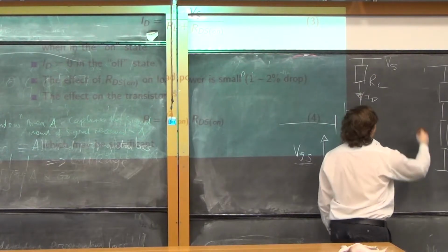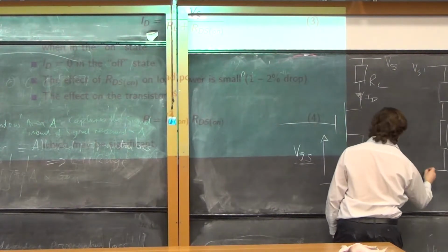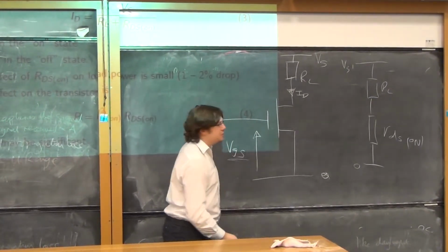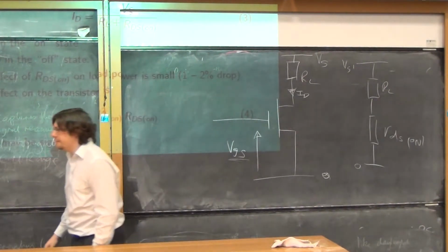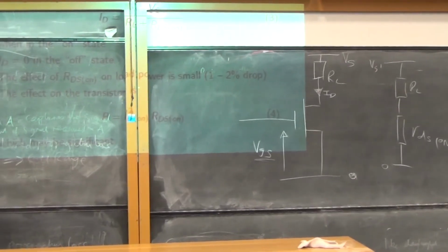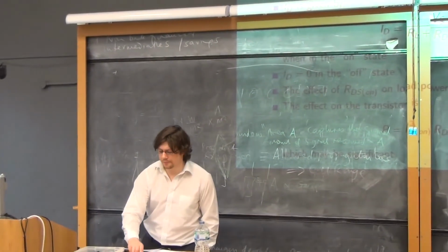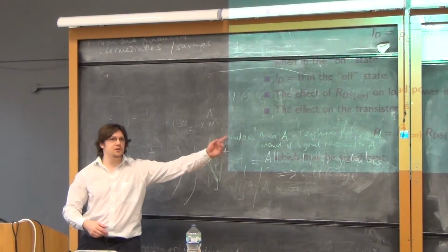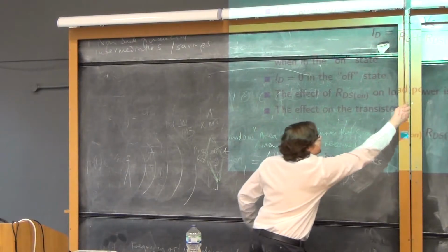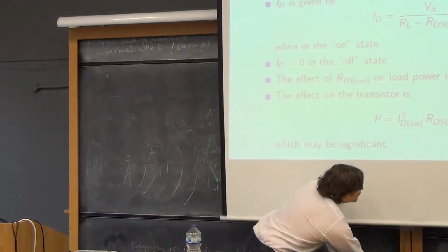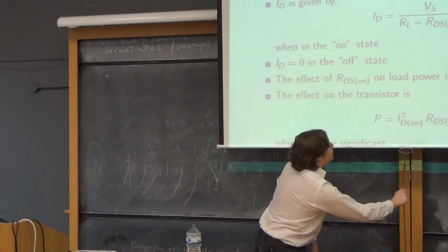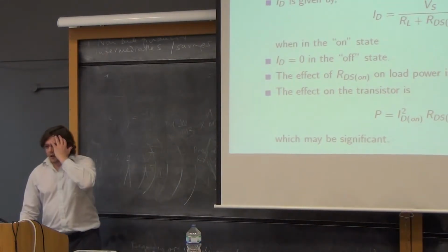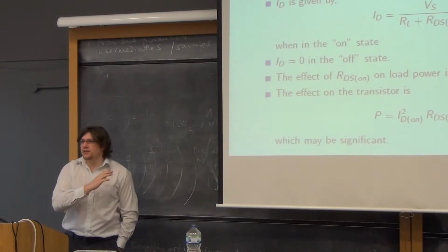So really it's just two resistors as a potential divider. So all this transistor malarkey is just dressed up Ohm's law, really. So we do ID as Vs upon the sum of the two resistors. And we can say that that's in the switched on state.